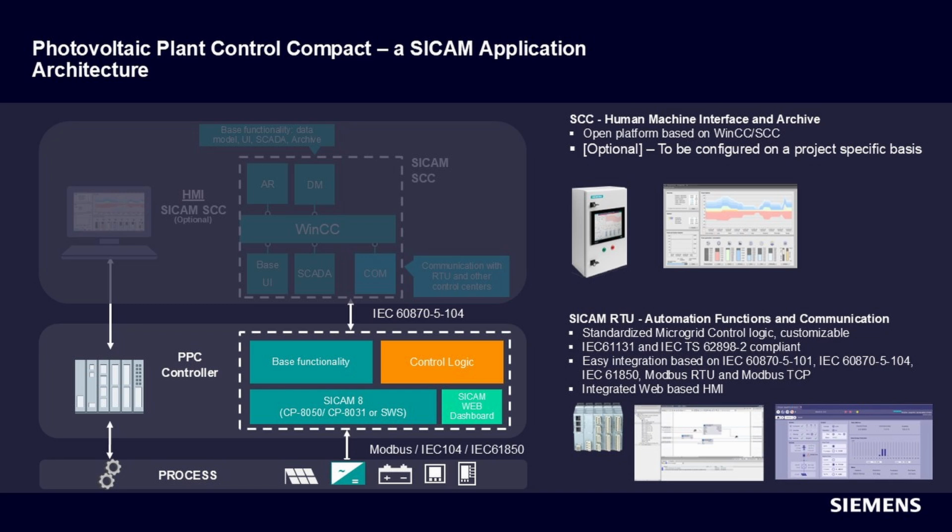The controller runs on a CP8031, but we can also operate this control logic on a CP8050 or as a software-based solution, basically using SICAM 8 platforms. However, the controller includes not only the logic and the communication protocol that enable it to interact with the process and remote supervision systems, but also the integrated SICAM Web HMI or dashboard.